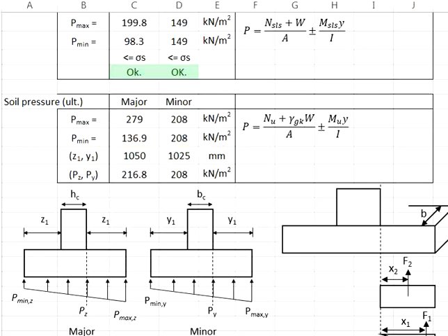In order to do so, we will need to first get some dimensions, as well as the soil pressure at certain locations, particularly the soil pressure at the surface of the column. Why is it so? Because later the moment will be acting on the surface plane of the column. Same goes for the shear force.